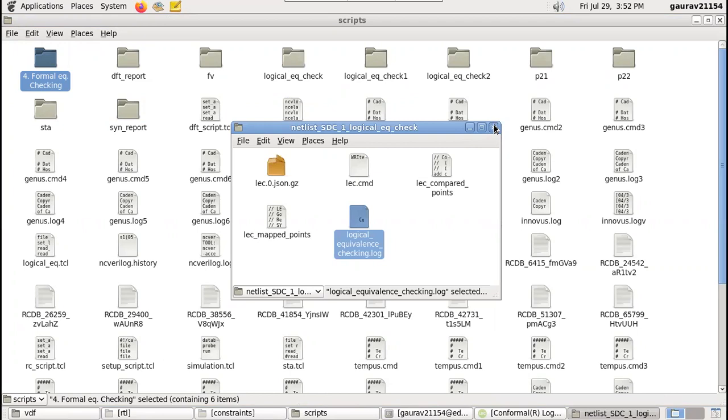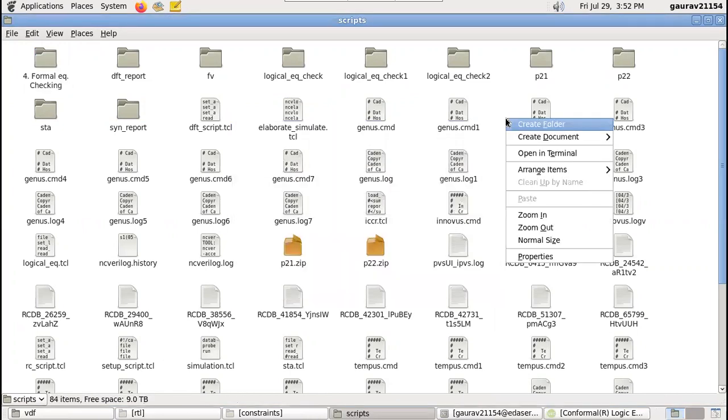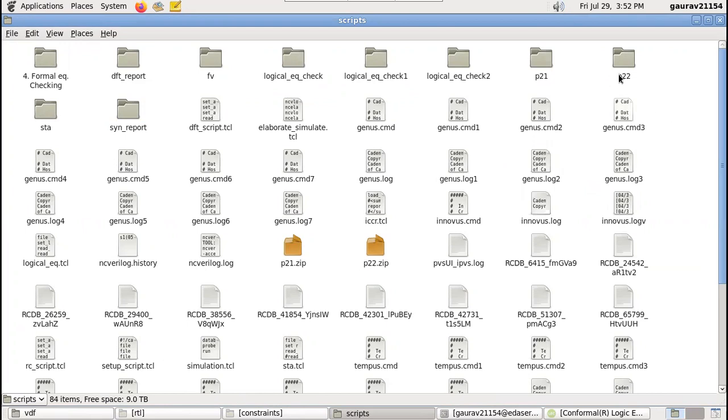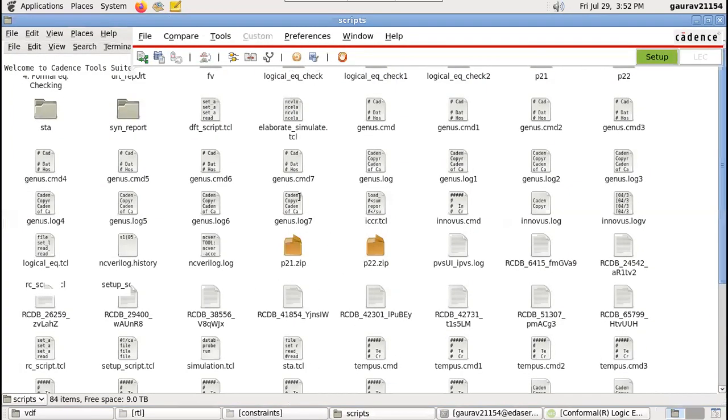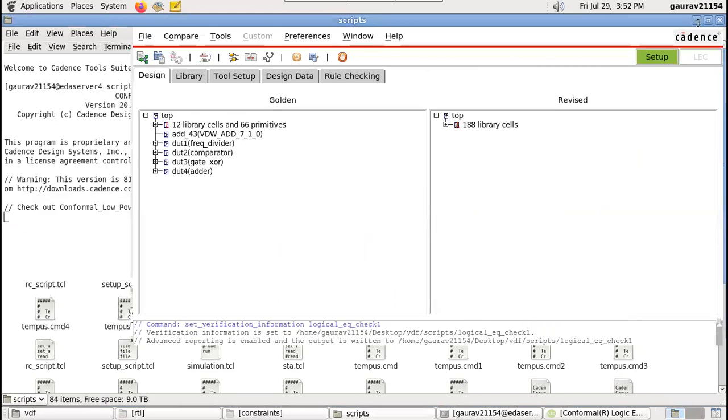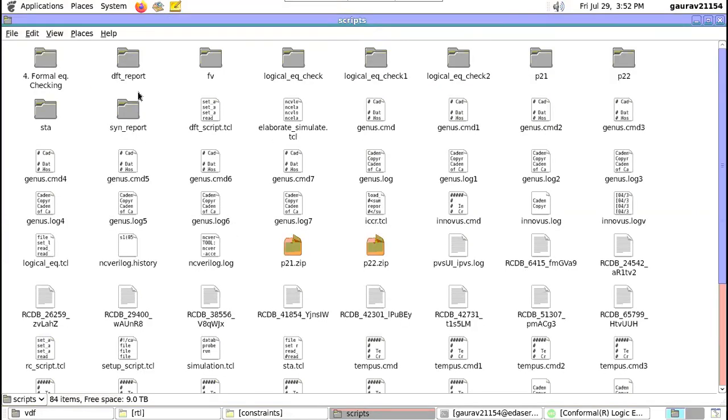Now we also have to take care of the stuck-at faults which might occur in the design due to error faults. To detect the fault efficiently, you have to insert the scan cells. You can insert the scan cell by a TCL script. I am not doing that. So this is the RTL. I am doing up to the synthesized netlist.v we have generated. So our logic synthesis part is getting completed.